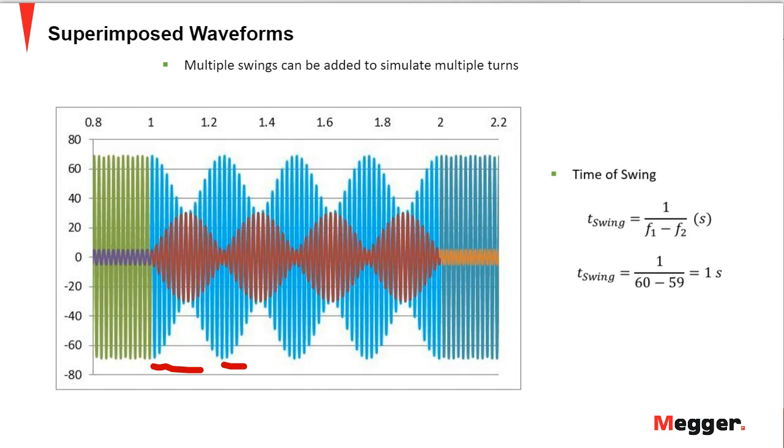And this is not just something theoretical. In real cases, you can see that those oscillations take some time, and there are several cycles of the oscillation, and you want to make sure that your protection is both secure and dependable for those types of operations, right? Now, what we do is we declare the time of the swing, as we saw before, as the